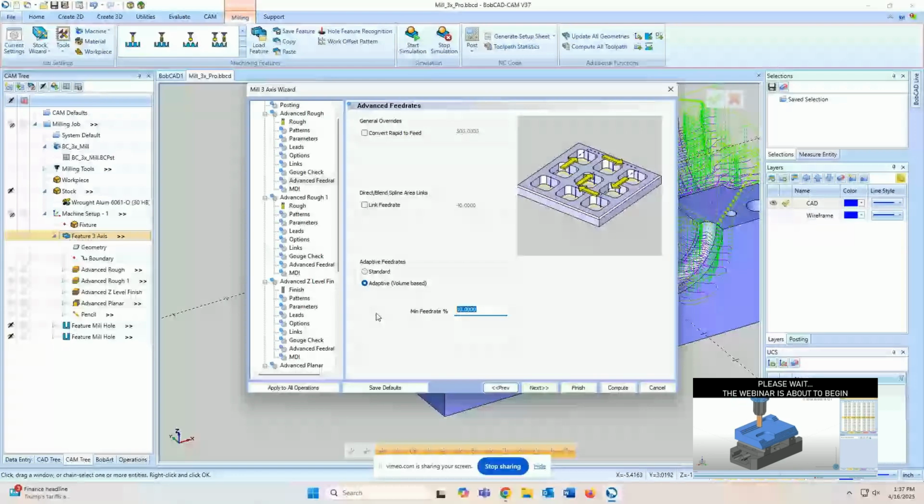And when it gets into larger material at a time, like into these corners, the software can calculate how slow the tool needs to move to keep a constant chip load, and that can reduce chattering at the machine. So it's going to calculate the certain amount of material per tooth of the tool as it's getting into the material here. If it needs to get all the way down to 6 inches per minute, 10% of the feed rate that I have, it'll go anywhere between 6 inches per minute to 60 inches per minute to keep a constant chip load.